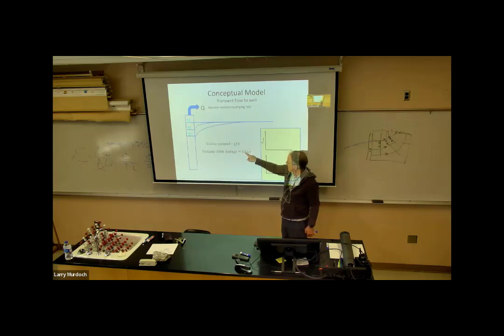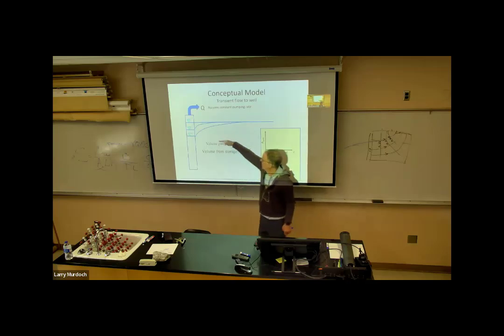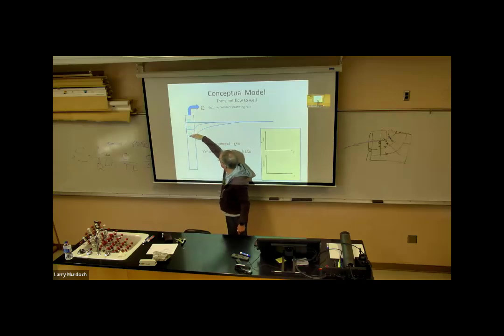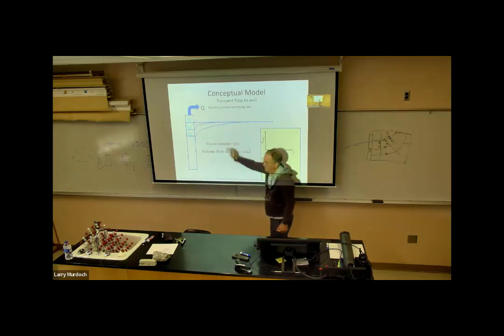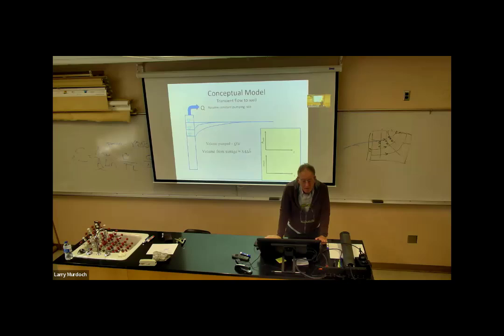And we have area increasing and delta H increasing, both of these are increasing. The drawdown is increasing with time, and we're influencing a bigger area. So both of those things are changing. There's the radius of influence that will determine the area.